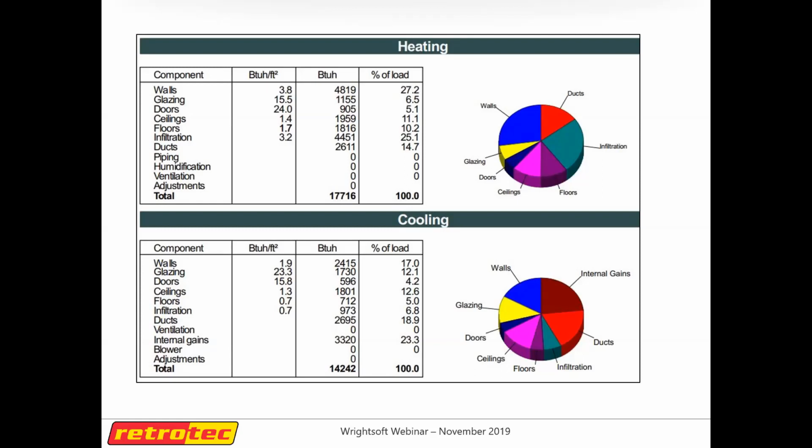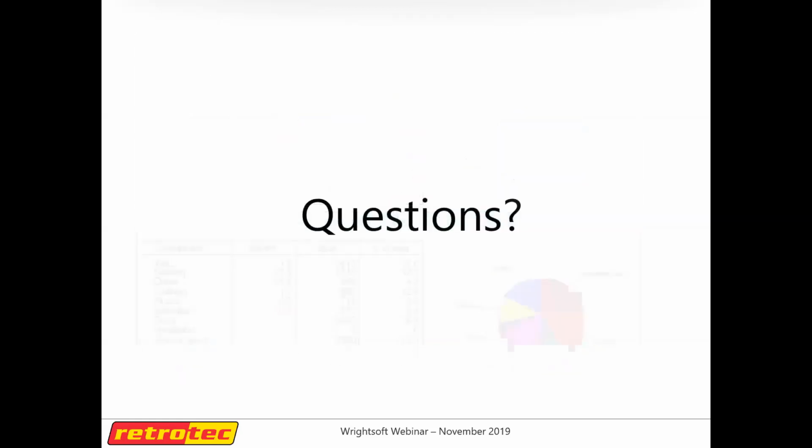So we're about halfway through. Lee, what kind of questions do we have? Looks like Matt, you typed in a 970 BTU per pound. Wasn't sure what that was in reference to. That's the latent load of water. I didn't know if it was 960 or 970, but Matt jumped in and told us it's 970 per pound. And I say pint of water, but Matt, as you know, a pint's a pound the world round. If you're at sea level, a pint of water and a pound of water are the same thing. But if you go above sea level, it becomes different.